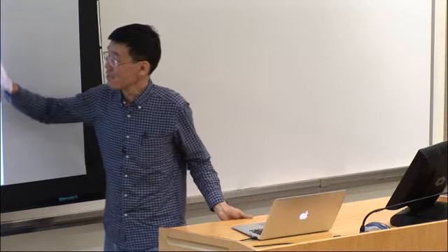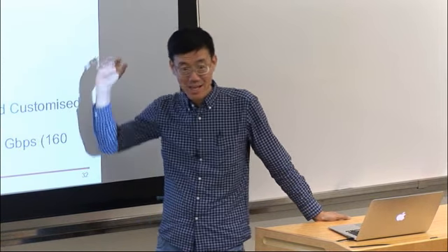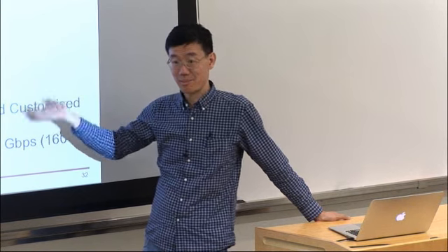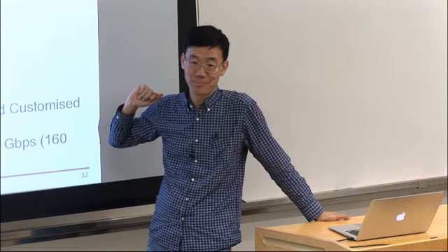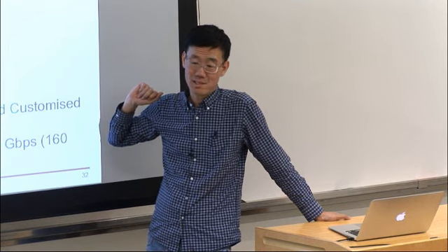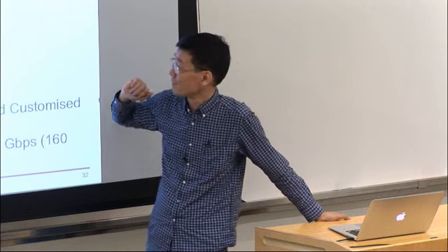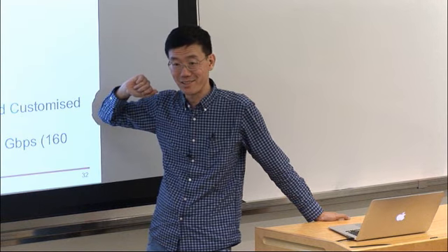Naive versus the hand tuned? Naive is if you take the source code to our implementation in C and pass it through the tools, you get an implementation, and that's the kind of performance that you get. This is Vivado HLS. But is the hand version like 6 months of work? Is that what you're saying? The hand version's about 6 to 12 months of work.